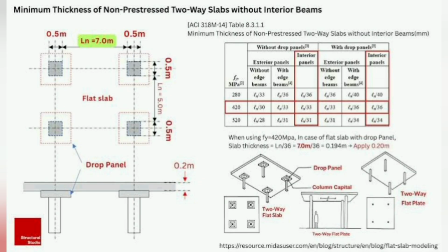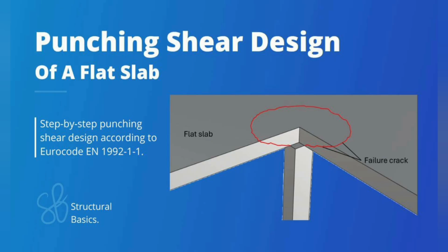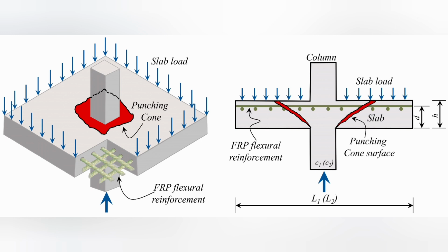However, there are significant drawbacks. Flat plates have poor resistance to lateral loads like wind or earthquakes. They have relatively low shear capacity around the columns, which can lead to punching shear failure, and they can experience excessive deflection in longer spans.